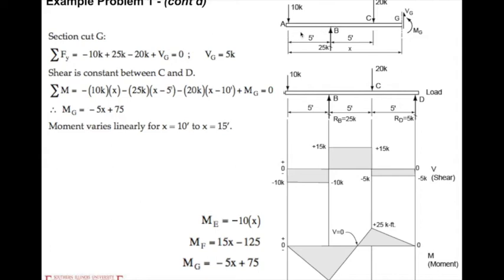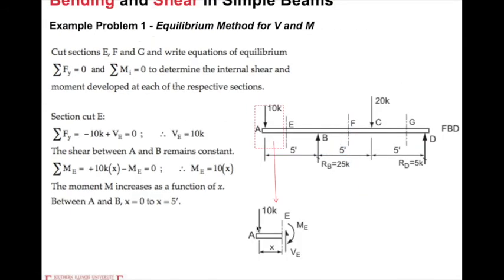This is a concave downward curvature which can shed water downwards. So that means the moment sign is negative, that's minus 10 times x, instead of the solution we solved, which is 10 times x. So just pay attention to this one. There are two different sign systems.